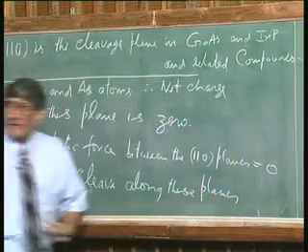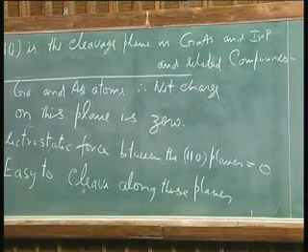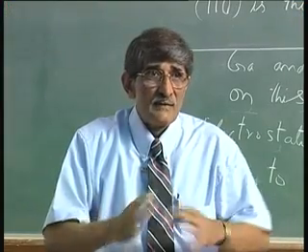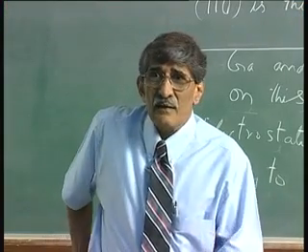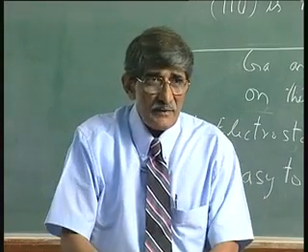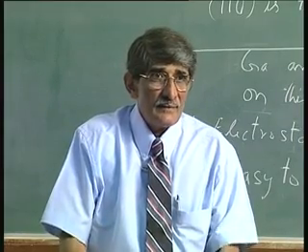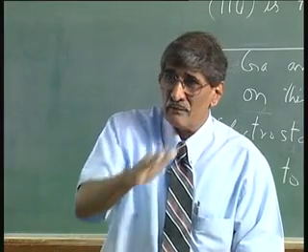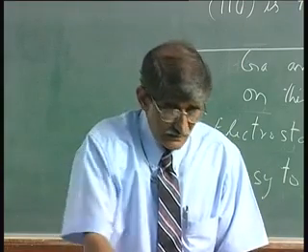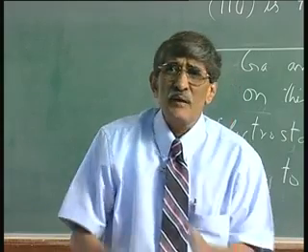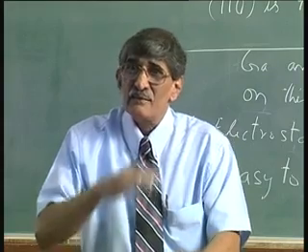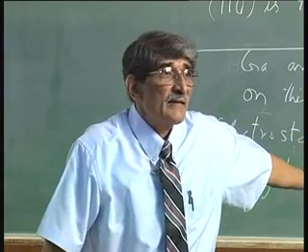Okay. So, this is what I want to drive home, because the entire idea of taking a look at this crystal structure is to understand some of the properties which are relevant to technology. And what is relevant to technology is, if I scribe and cleave in silicon, it will cleave along the 111 plane. How do you cleave? You just draw a line, scribe to a depth of about 1/10 of the thickness of the wafer, then apply a little bit of force, and it will just cleave along that plane. That is what is meant by the cleavage plane.